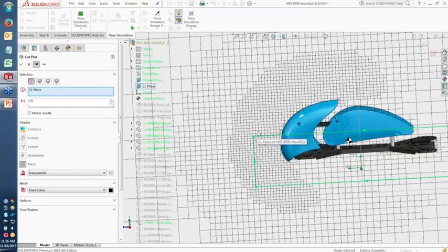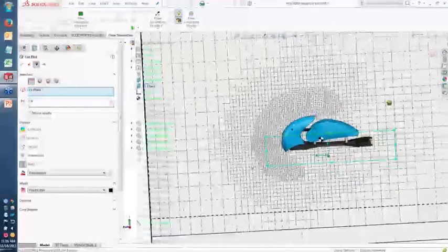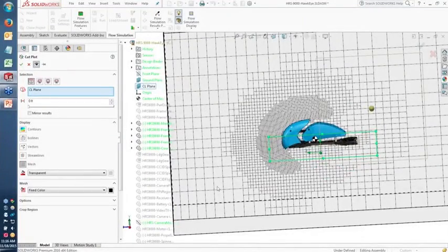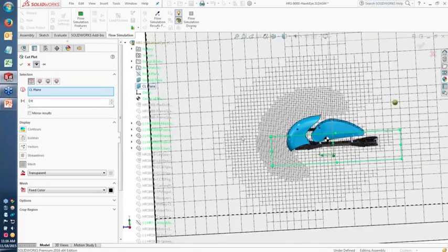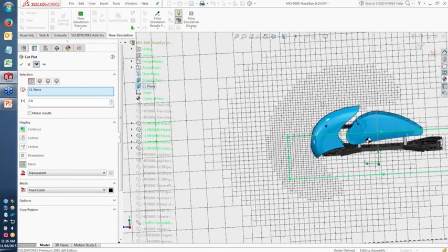And here you see the effect of those zones that I've created. So out here in the front, you can see that the cells are pretty much the same size they would have been if I hadn't used this option. But now I've got these two refinement zones going down 1 and then 2 levels, basically, from the mesh that would have been at the face of the object. And so now that extra refinement is contained only to right in the front of the craft, which, if you're kind of into aerodynamics problems, you know can be real important. And when we go look at some results afterwards, I'll show you some of the differences in what this extra refinement can make in the results and how much impact it has.